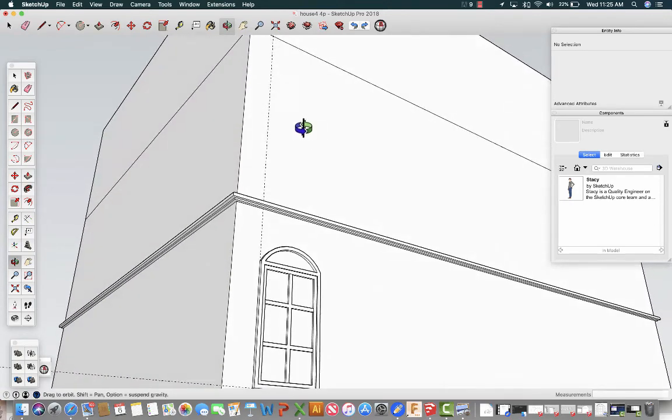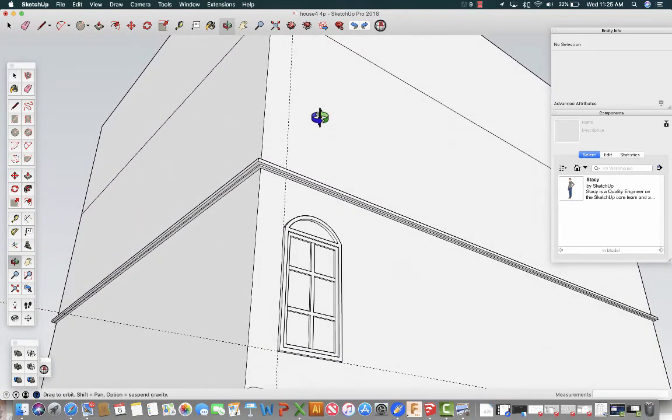So I have that first window, and we decided that it's going to be separated by 1 meter to the next window, right? So the distance when I copy this window to the next one should be 2 meters. So it will have the 1 meter in between and the 1 meter for the window.